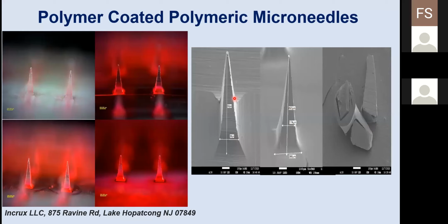So once we were sure that we can use 4% ethyl cellulose to coat, the core microneedles were prepared with PVP, and then coated with ethyl cellulose. The main reason we selected ethyl cellulose is that it should be water insoluble, right? Ethyl cellulose is water insoluble, but it's semi-permeable. It's hydrophilic, but it does not dissolve. So it's a semi-permeable membrane.